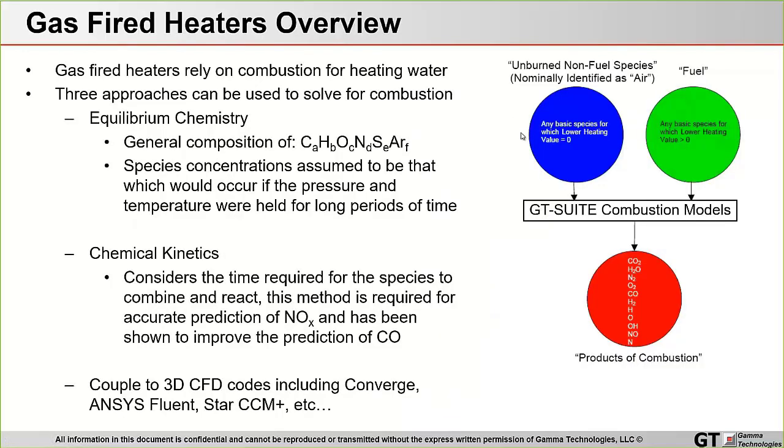Now, when it comes to transitioning to gas-fired heaters, they rely on combustion for heating the water. And there are three approaches that can be used to solve for the combustion phenomenon in GT Suite. The first and most popular option is to use the equilibrium combustion model. And that assumes there's a general hydrocarbon composition of carbons and hydrogens and so on, as you can see the list of molecules that are supported.